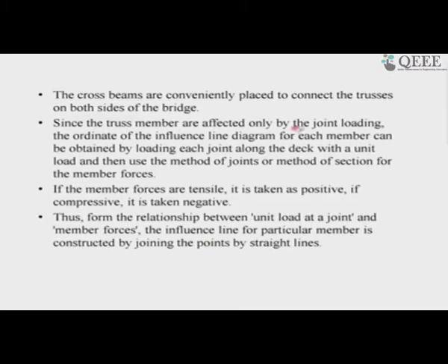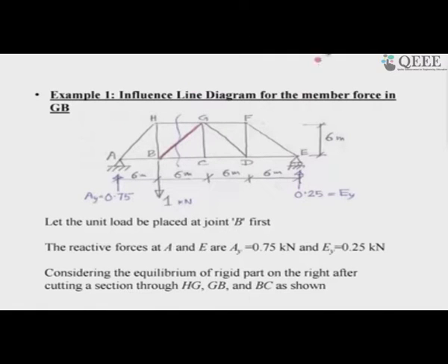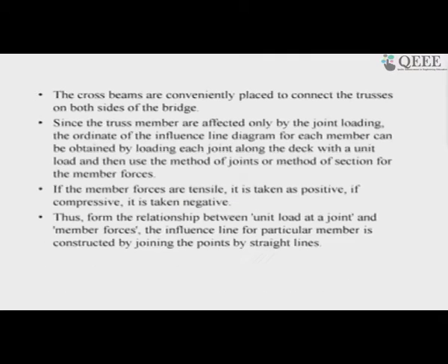And the influence line diagrams are straight lines, as we have learned earlier, because if you release a structure from its support or member forces, it becomes unstable, and that's how you have the rigid body movement of the parts, and that's how it becomes straight lines.